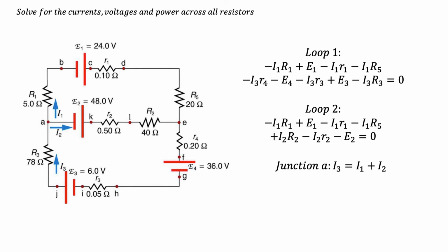At this point, we note that the equation derived from loop 1 relates all variables along the wire with current I1 and along the wire with current I3. We also note that the equation derived from loop 2 relates all variables along the wire with current I1 and along the wire with current I2. Thus, it will no longer be necessary to derive another equation from loop 3 since it will be redundant. Generally, we only need n-1 loops to solve the problem.